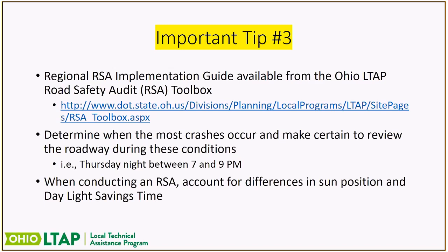One other thing, and this just comes through the experience of having done over 30 different RSAs at different times of the year and areas of the state, is make sure if this is a factor that you put it into the mix. Daylight savings time can be an impact when you're looking at a roadway.